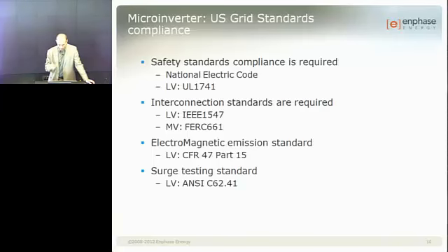Now there is actually an interesting trick, which is that on a 208 installation or even a 480 installation, we have a cable which has all three phases in the cable, and at every connector we take out two of the three phases and we rotate every time. So you pick L1, L2 on the first, L2, L3 on the second, L3, L1 on the third, and it self-balances the system out. So we can do a balanced three-phase installation with single-phase inverters without any design, it's really brainless.